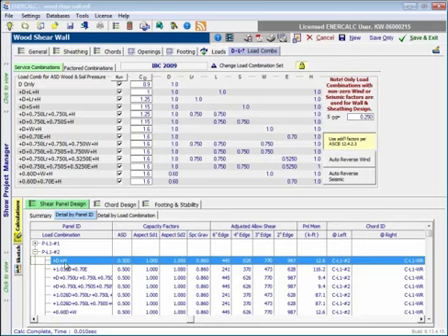What that means is that the special design provisions indicate that we do certain things for determining the allowable strength when resisting wind load combinations, and we have to do some potentially different things when we resist shears due to load combinations that incorporate seismic effects.